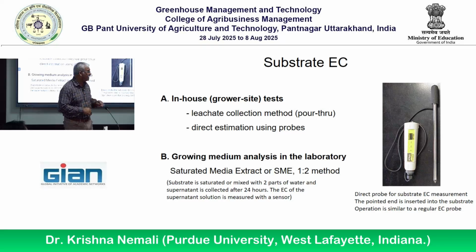Okay, but the advantage is you insert the probe and you get a quick number, so you don't have to worry about the other process that we do this afternoon, pour through, which I'm going to explain in the next slide, is the right one, but it's a little bit more cumbersome. It takes some time. Okay, so you can measure exactly the concentration of ions in the pores. That's called pore water conductivity. Okay, just the solution in the pores, you can do that.